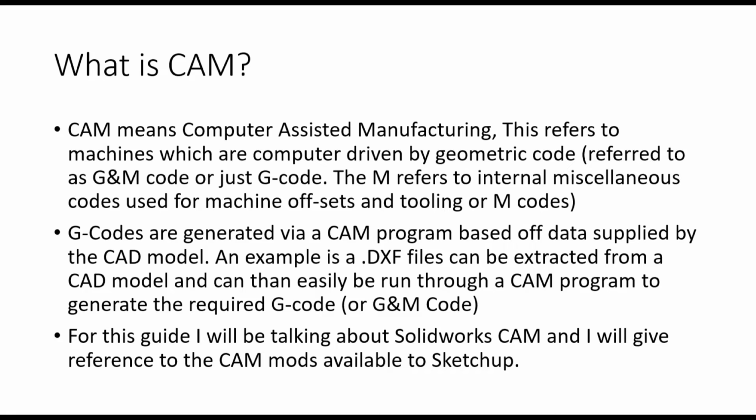However, there are nesting programs, and that's awesome because let's say you've got an entire kitchen: overheads, multiple lower cabinets, island bench, just heaps of stuff. You can nest all of that at once. Basically get all of your parts as DXFs, throw them into a nesting program, and it'll nest all of them really efficiently to give you the minimal amount of waste.